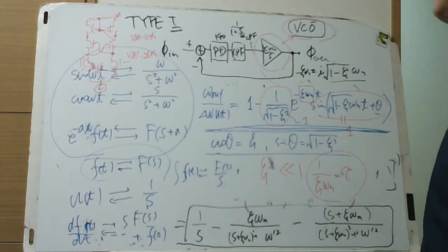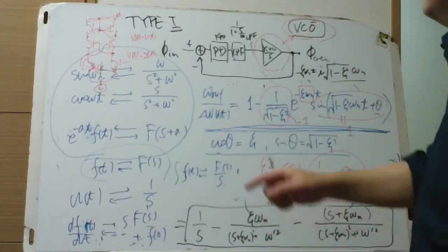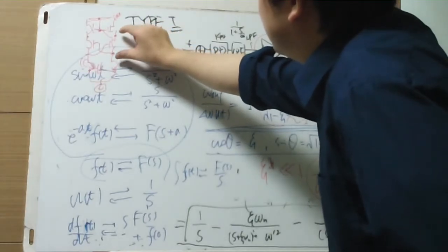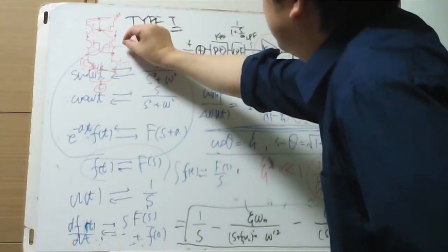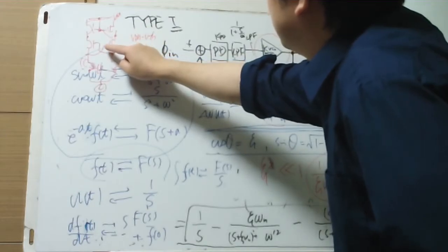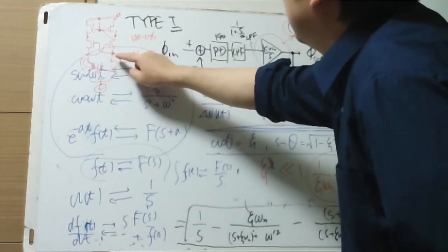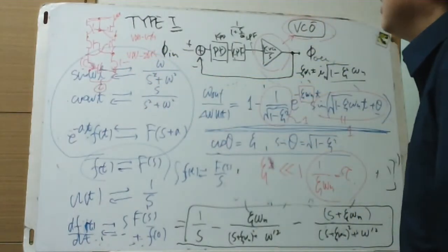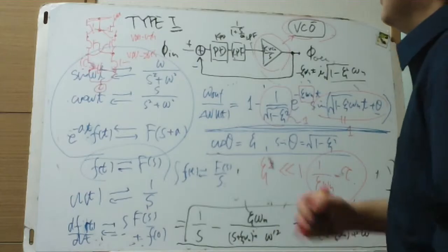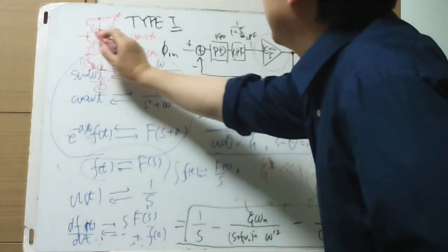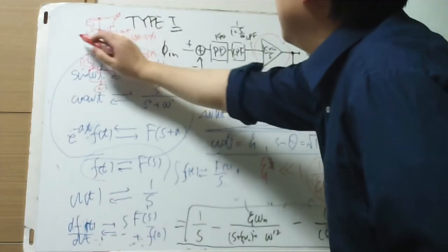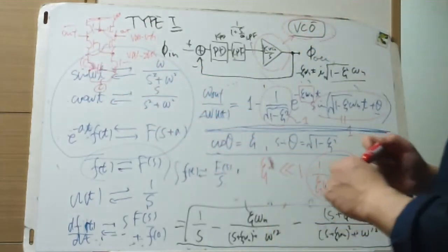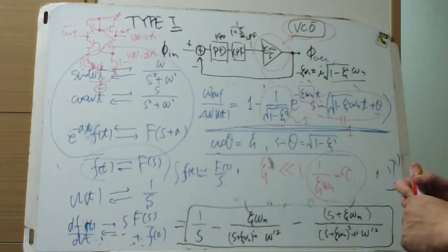The largest voltage is VDD minus VTH here. This is on, and this needs to be VTH. The least output voltage is VDD minus 2 VTH. So this is the output node, and the output node bar, maybe.